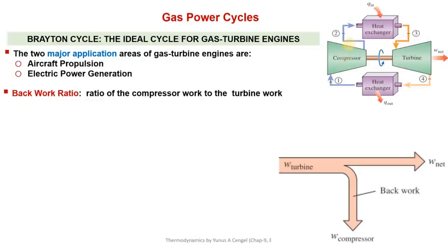But in a gas compressor, v does not remain constant; the specific volume changes with pressure also. That's why the work input to the compressor will be very high compared to the equivalent work input in the case of a liquid pump.